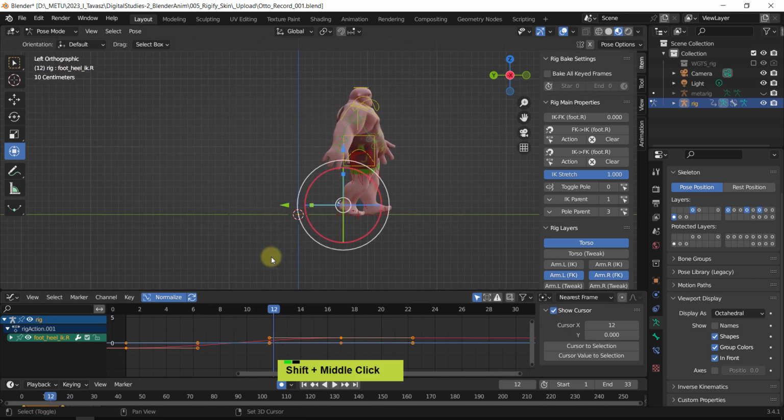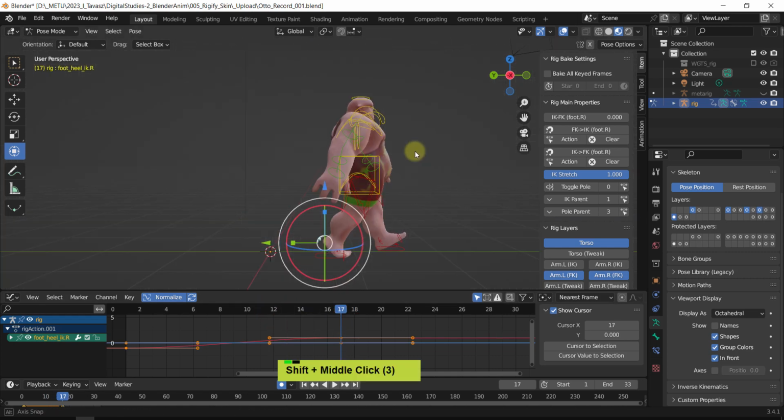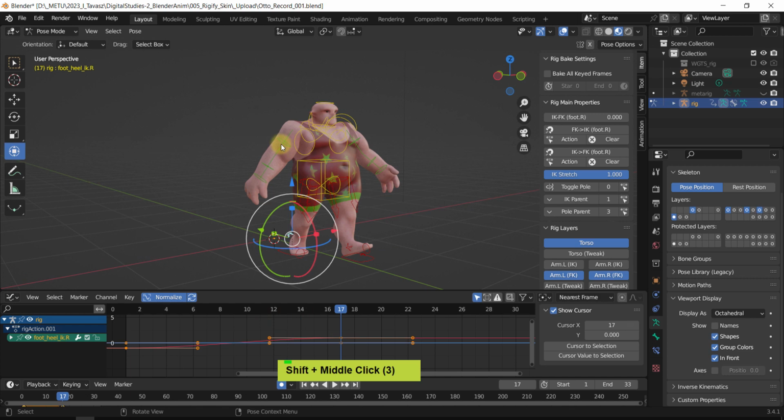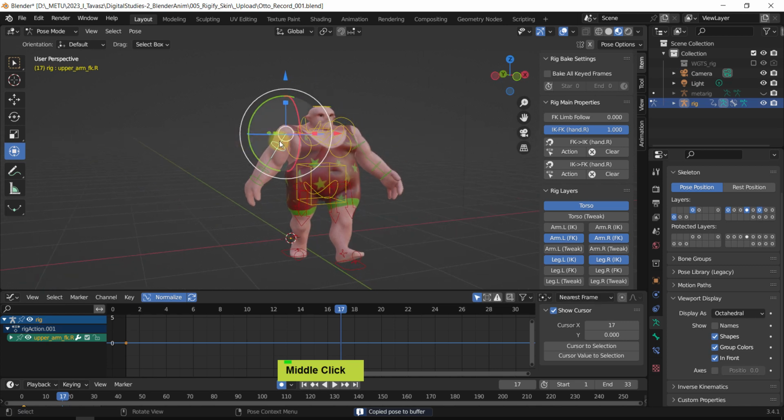Okay, and between these two, now it's time to first of all switch the arms. To easily switch those, we can select this one and press Ctrl C. The cursor is in the 3D viewport, so pressing Ctrl C copies the position, the keys, and everything of this particular thing. If I press Ctrl V, it will just replace the existing, so nothing changes basically. But if you press Ctrl Shift and V, that's paste opposite. So now the other hand has the same position as this one.